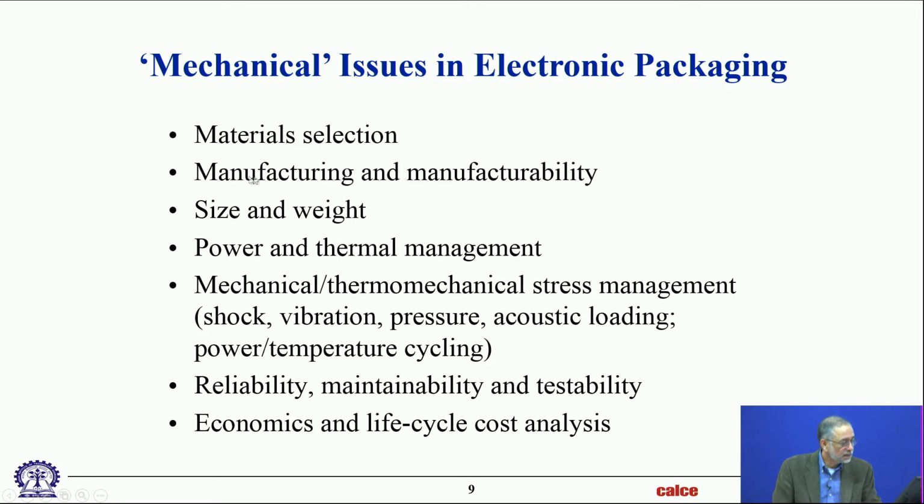Okay. Then comes the next step. As I said, you could take the best material in the world, do poor manufacturing with it, and kill the material. Be so full of defects that it never survived. Especially at the length scales we are talking about in electronics, the material defects is everything. The material dies because of internal defects. All materials have defects, and it's the defect density that'll make your product different from the next person's product. And controlling those defect densities is absolutely key, which is why semiconductor manufacturing, which is at the lowest rung of the chain of electronic products, is so difficult.